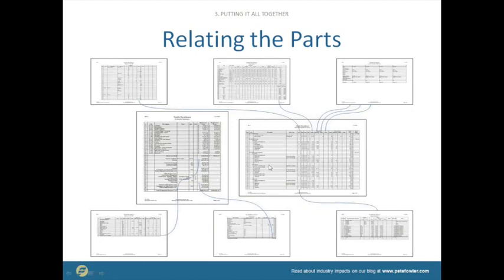Where are we getting those materials? Well, we called 3 different material suppliers, and they all gave us relatively similar figures for the specified windows. It's going to take 3 man hours per window to install, and we're going to use the Sonneborn sealant that costs $7 a tube if you buy it in bulk. And to get it to the site, it's going to cost this much.